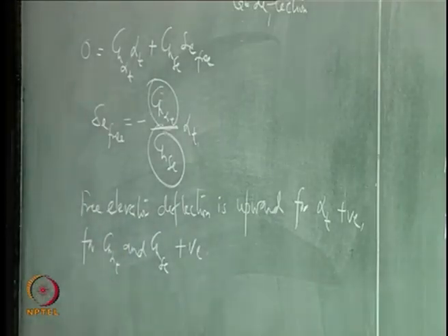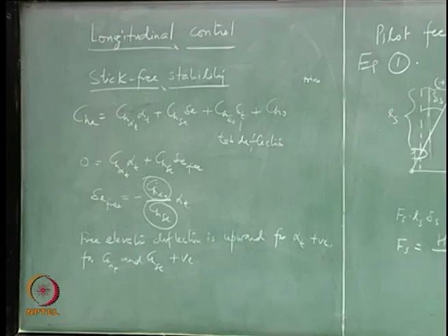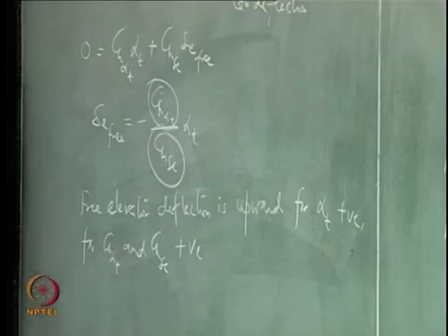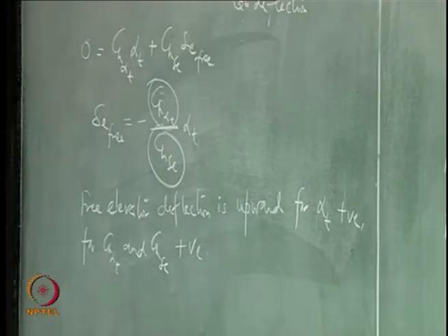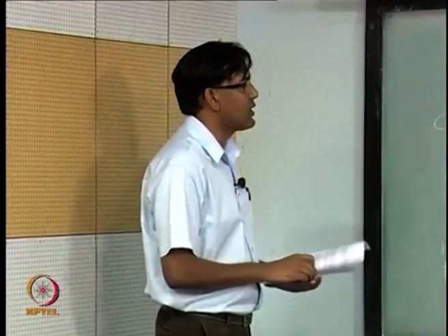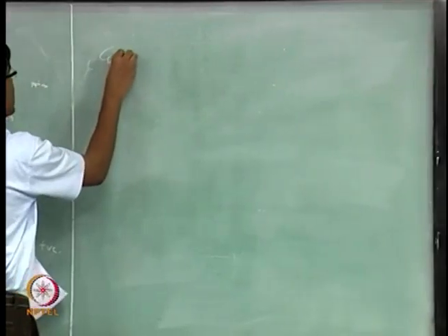and they are positive, okay. So, there people have done some measurements and they have found that these two parameters are positive, okay. So, automatically elevator should show an upward deflection, okay, without doing anything whenever there is a flow over the airfoil. Let us look at what happens to the lift coefficient of the tail in such a situation.